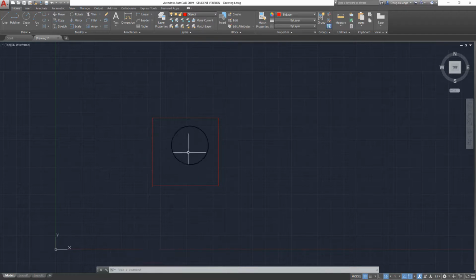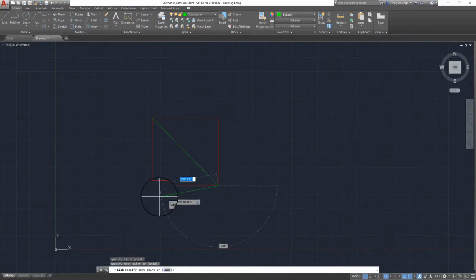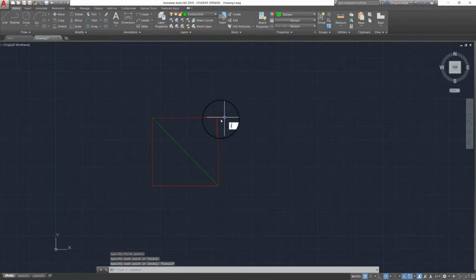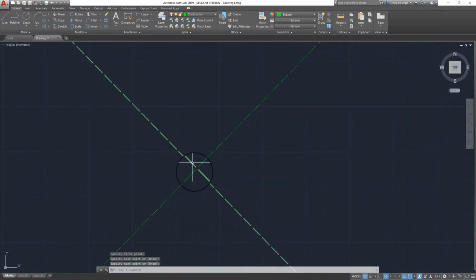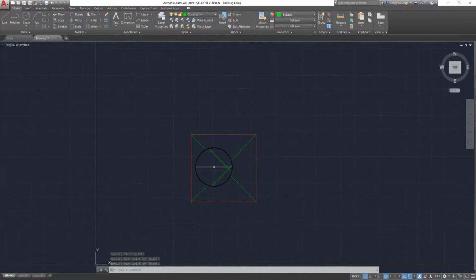Now say I want to find the middle of this box. Well, I could draw with my object lines some more, but I might not want to do that. Maybe I'll use my construction lines instead. And I can draw another line like this. And another line like this. And you'll see that I used a text command to open that up, and we'll talk about those later. And now I've drawn 2 lines, and that helps me find the center of my box.